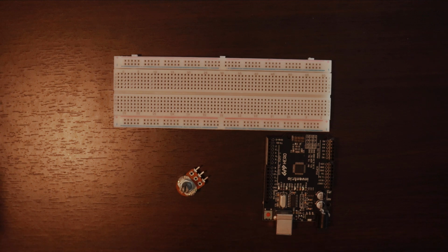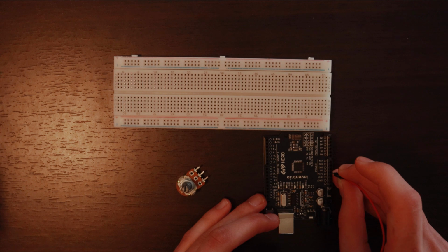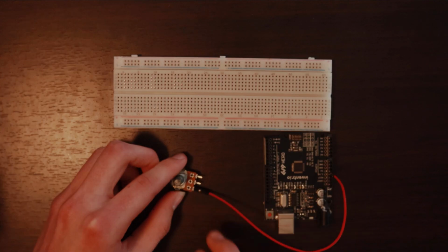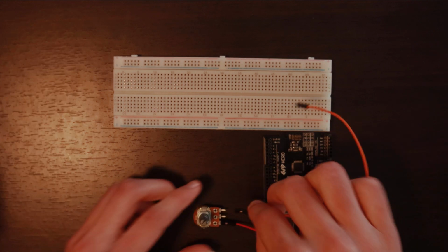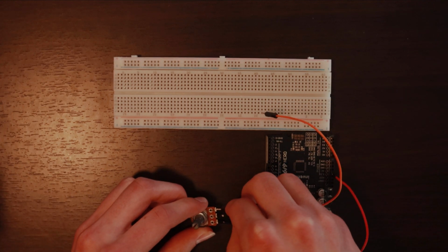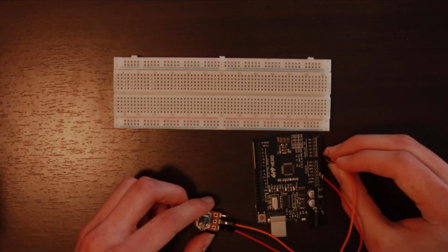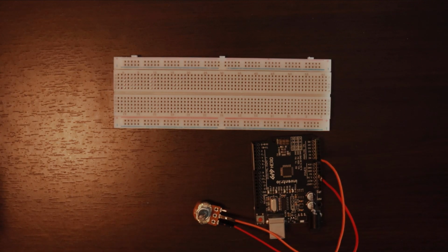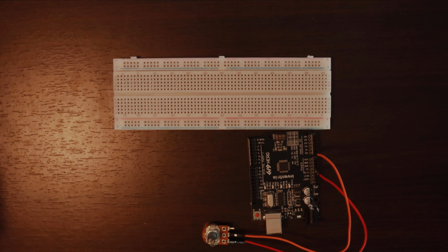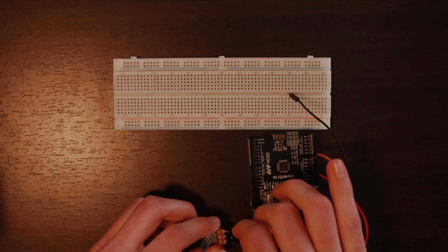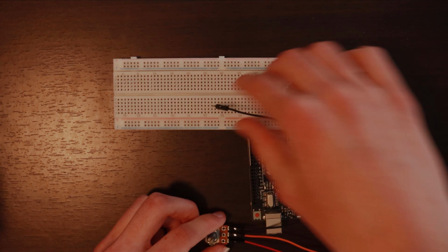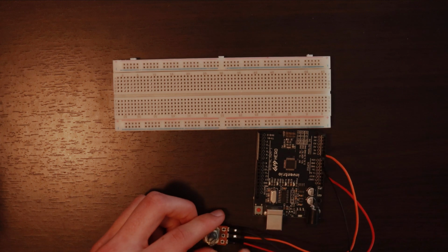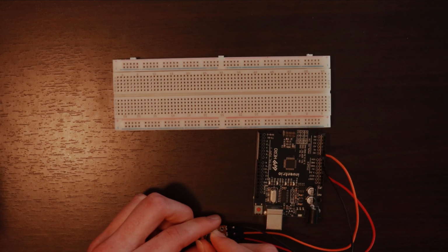First, we'll supply power to the pin on the right or bottom by connecting a wire from the 5-volt pin on the Arduino. Next, we'll connect a wire from the middle of the potentiometer to port A0, which will allow us to read where the dial is located and use that in our program. The last thing we need to do is connect a wire from the remaining pin on the potentiometer to one of the ground pins on the Arduino. This makes sure that when the dial is rotated away from the positive pin, the LED won't light up.